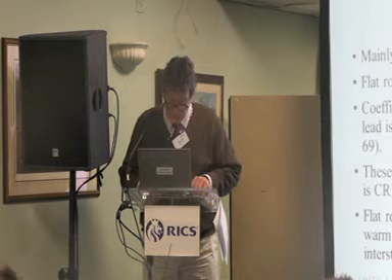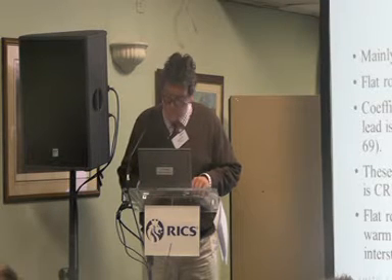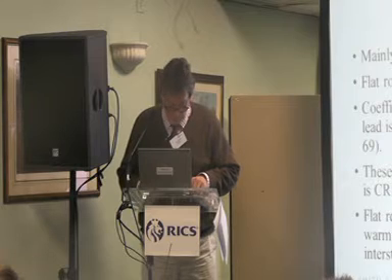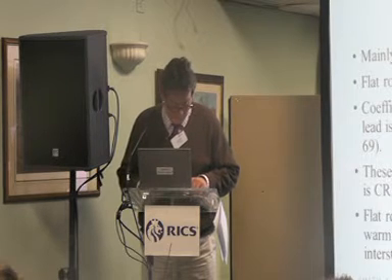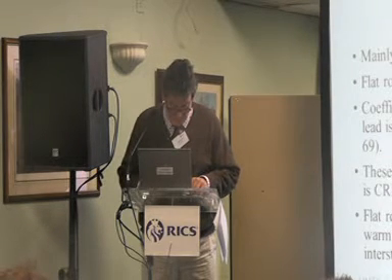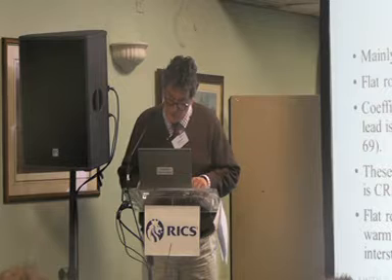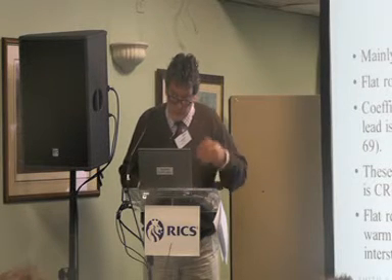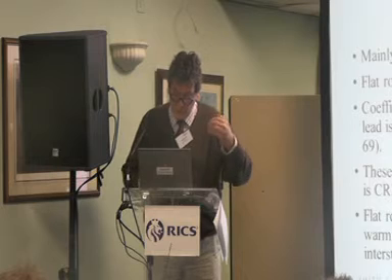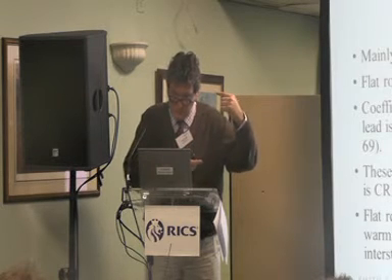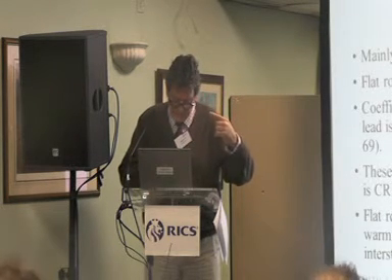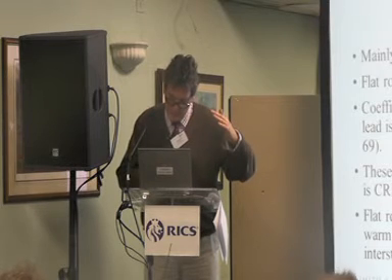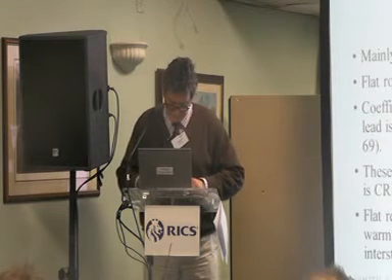I'm going to show you slides in a minute, but flat roofs must either be vented cold roofs or vented warm roofs. And the common factor is, of course, ventilation. If you don't have ventilation, you'll have what's called interstitial condensation. Interstitial meaning that the condensate, the water, is actually dropped within the fabric of the roof. Now I'm going to come back to talk about that later, but flat roofs covered in metal must be vented either above the insulation or below the insulation.